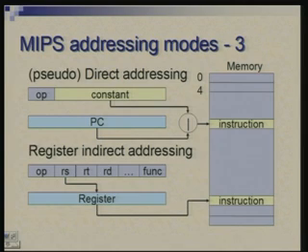It needs to borrow a few bits from program counter. This is the mode which we have in jump or J instruction or JAL, that is jump and link instruction. So, as you would recall, in these two instructions there is a 26 bit constant field, which together with 4 bits taken from most significant end of PC form 30 bit word address, and that suffixed with 2 zeros forms a 32 bit byte address, which is used to access an instruction.